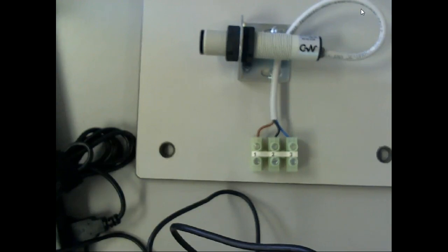Traffic signal light. The traffic signal light wouldn't use this guy. They have sensors, but those are not photo sensors. So those things are on 24 hours a day, 7 days a week. Some people call these dusk to dawn switches. So when it gets a certain darkness, they activate their load. When it gets a certain light, they deactivate it. Like city street lights. Just about all used to be, before they came up with these things, on timers.